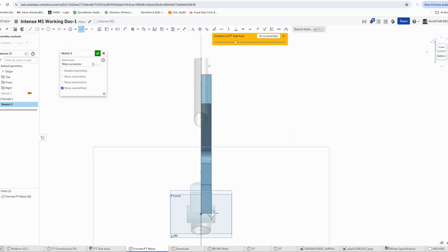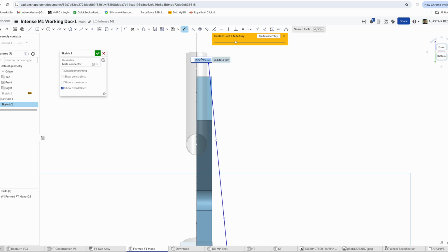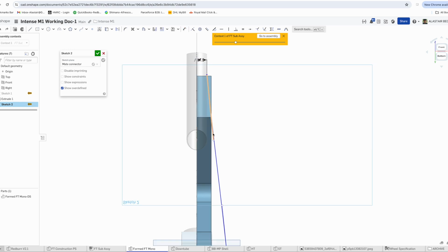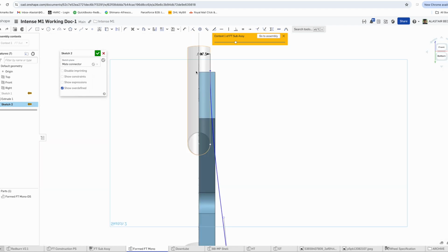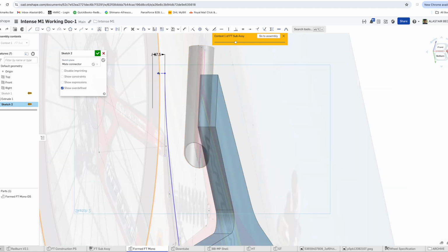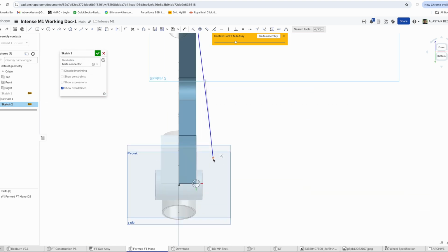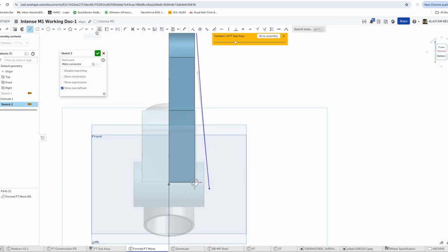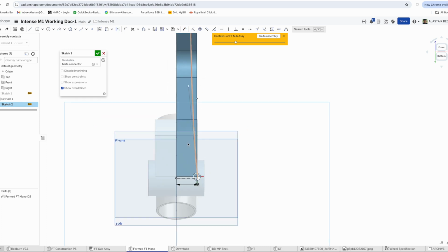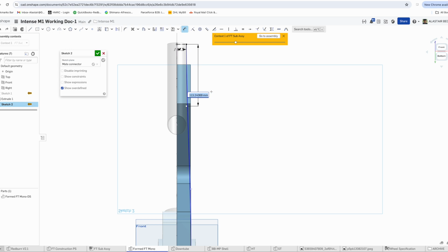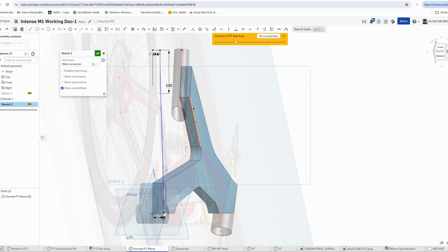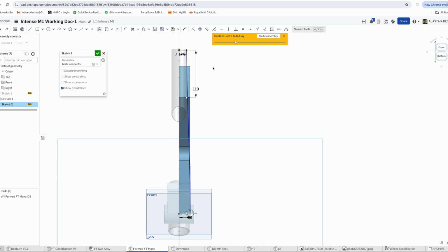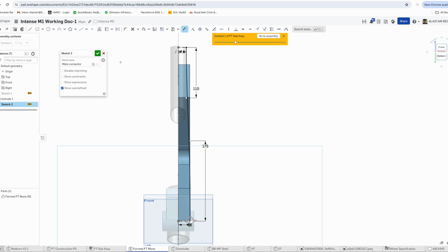So with this part, we're going to add that side surface across. That's going to help us get the pressed formed aluminium sheet fitting better at the seat tube, which is obviously narrower than the bottom bracket and the head tube. So I'm starting a sketch on the end of that formed part, and then we're going to add a spline curve that's going to give us a nice transition from the bottom bracket section up to the seat tube. We don't have to be super critical, and that spline could be a more complex shape if you needed, but for the purposes of this, it works quite well and gets everything a lot closer to where it needs to be.